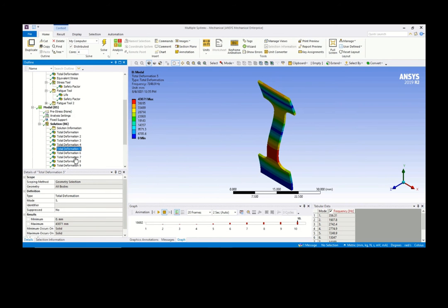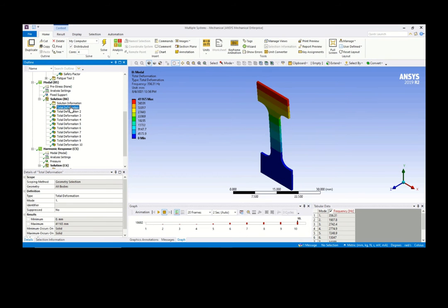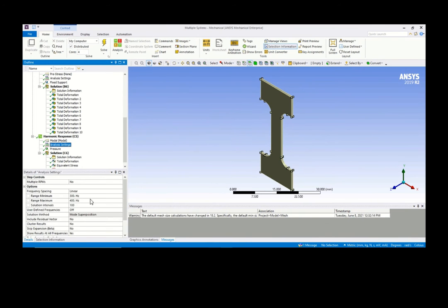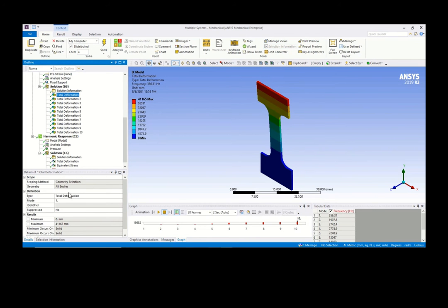All right, if we take into consideration the dynamic behavior of this so-called dog bone specimen to determine our displacements, here we combine a harmonic response with this modal analysis. In this setting, I'm looking at the frequency response from 300 to 400, because we want to see the effect of the first mode at 356 itself.